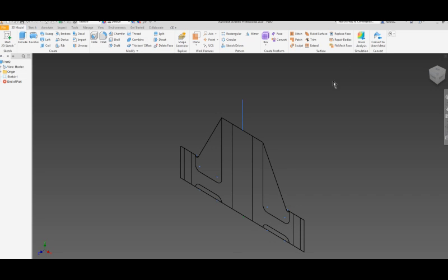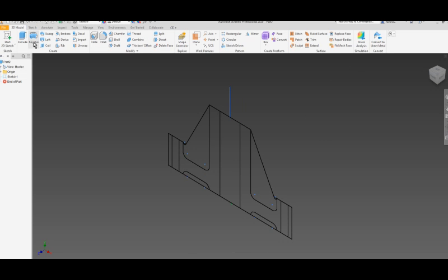That small line is going to be our center line, or axis of revolution. Let's finish our sketch. This time we're going to use revolve. We're not going to use extrude. So we're going to click on revolve.